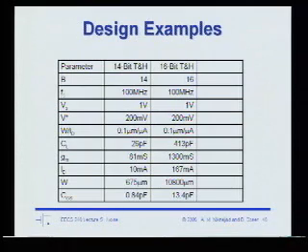Yes. So in the example, the V star is fixed, 200 millivolts or so. How does the choice of V star change over process scaling? Yeah, it changes in a kind of subtle way. A rough rule of thumb is that you should operate your transistor with a V star roughly n times Vt, Vt being kT over q, n being the subthreshold swing, right?